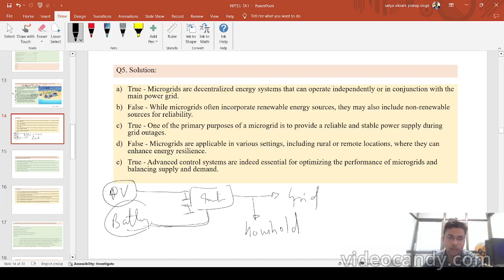Why am I saying that? Because for the generation of 230 volt RMS from an inverter, you need a DC link voltage of about 500 to 700 volt. The PV system is unreliable, due to the irradiance problem, morning peak and evening low.